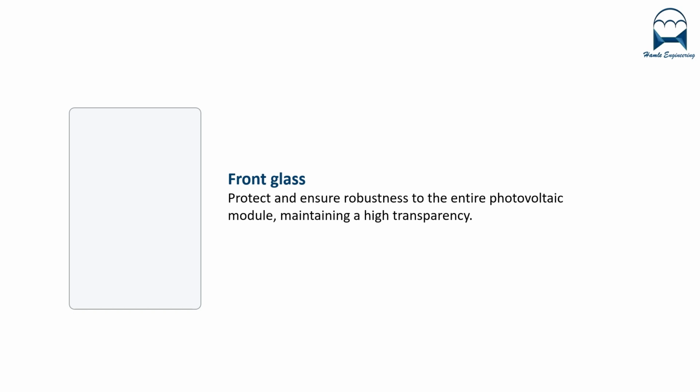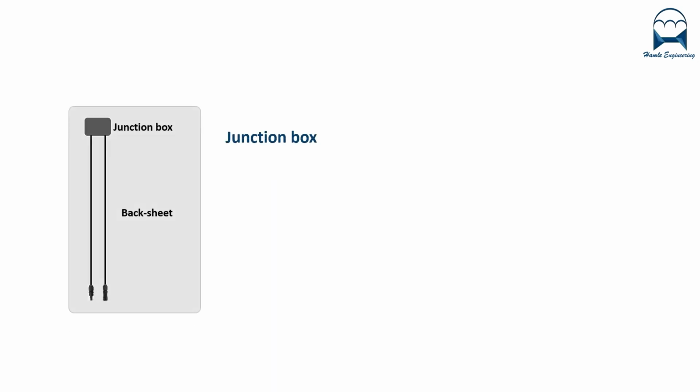It is important to pay attention to features such as quality of hardening, spectral transmittance, and light transmittance. For photovoltaics, some special glasses have been studied with a special pattern on their surface, ensuring a greater degree of light trapping. Choosing the glass carefully, checking these features, or adding anti-reflective layers can bring an overall improvement of the efficiency of the module.